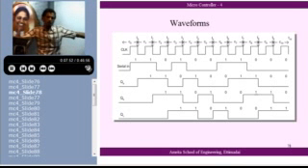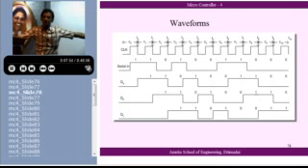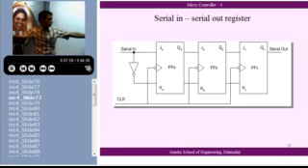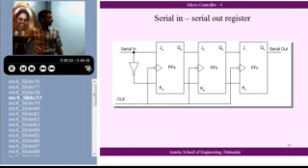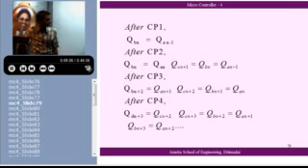Now, the rest of the story is as simple as what you have done earlier. See here? Okay, this I have shown here. What will happen? Whatever I explained, I put here. At every clock pulse, data is getting shifted. Now, the transitions occur at the successive negative clock edges.